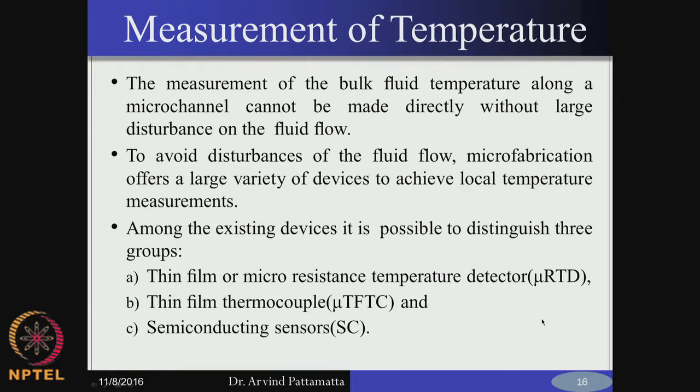But in all the conventional measurements that we use in heat transfer, using RTDs or thermocouples or temperature sensitive paints, we do not measure temperature, but the response to the temperature in terms of current or resistance or voltage. So, this is how we indirectly get it, and we know the calibration of current versus temperature or voltage versus temperature, that is the behavior of how the current or voltage or resistance changes.